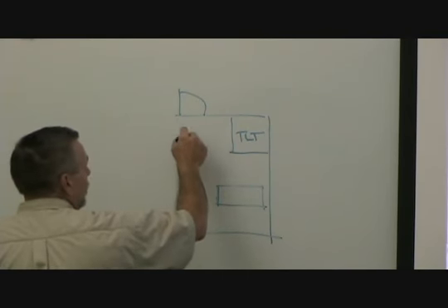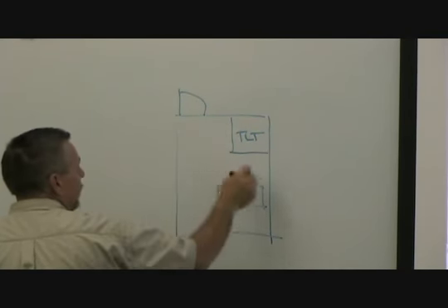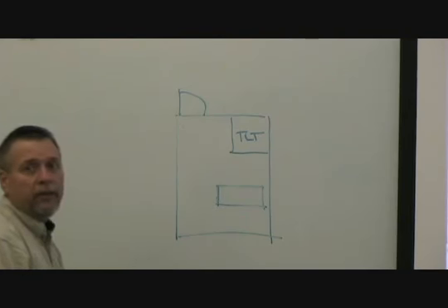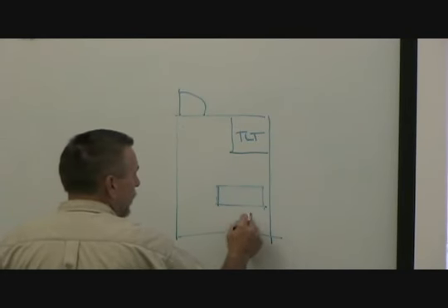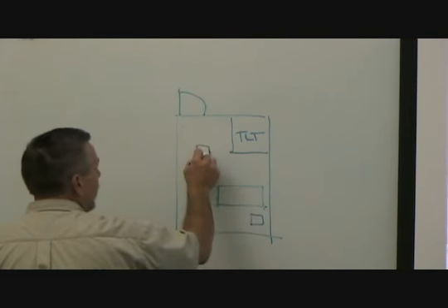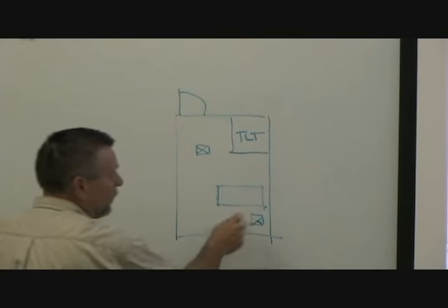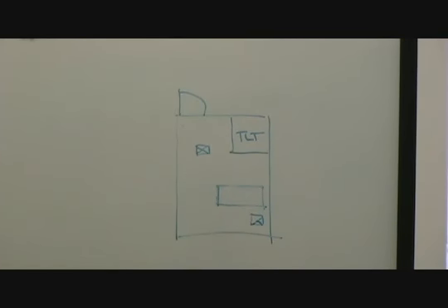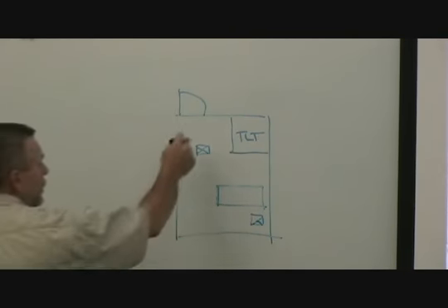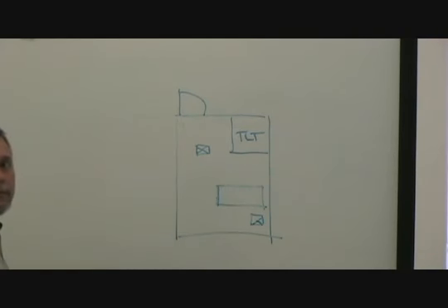So we don't want a return over here to drag air back to the nurse coming in the door. In an isolation room, you want that return and supply diffuser here so that you're creating the airflow pattern across the patient and out the room to protect people coming in the room.